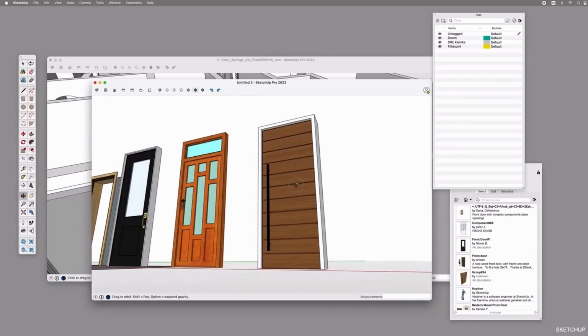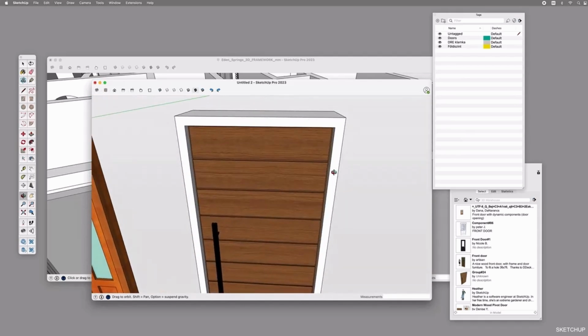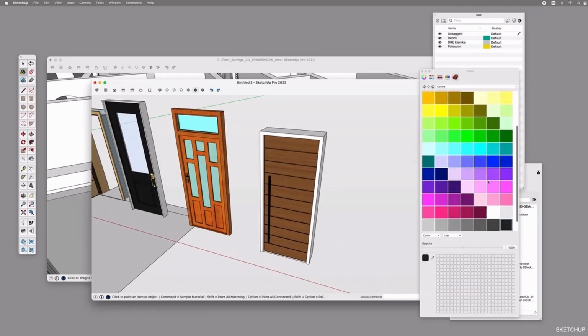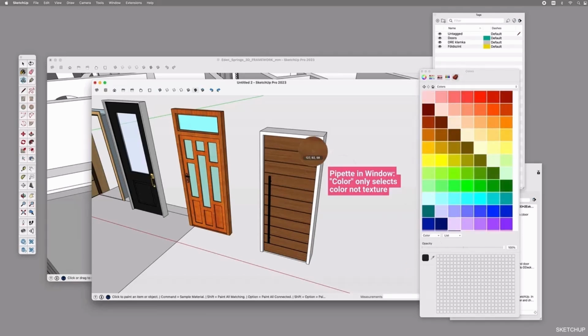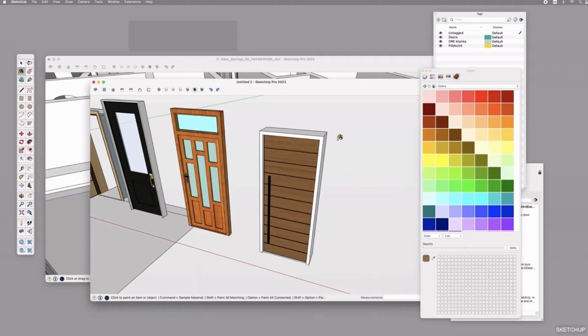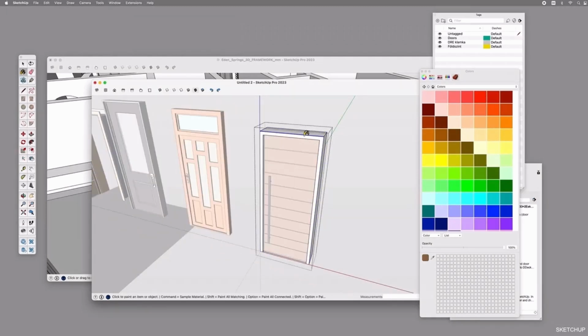I would like to show you how to select a foreign material. When opening my colors using B for bucket, there is a little pipette below. If you select this pipette, it selects all colors you can see within your monitor. But this is not what we want. We want to select the material, and by simply holding down Command using your bucket tool, you can see that a slightly different result will appear. You now chose the material and not the pixel color. Even though it's also a pipette, it's still a different selection. We can now select our frame and colorate it with the chosen texture.